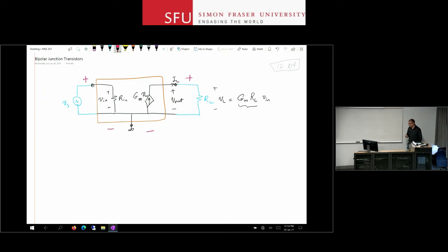You know how to deal with a resistor, you know how to deal with capacitors and inductors, and physically you know how to make all of those. A resistor is a piece of any conducting material. A capacitor is 2 electrodes separated by some gap between them, and an inductor is a winding, right? So we know how to make them. We also know how to make a diode. We take a semiconductor, we dope one side of the semiconductor with, let's say, N dopants and the other side with P dopants, make sure they have a proper interface between them, and you get a PN junction that behaves like a diode. And it has that exponential current-voltage relationship that we find very interesting.